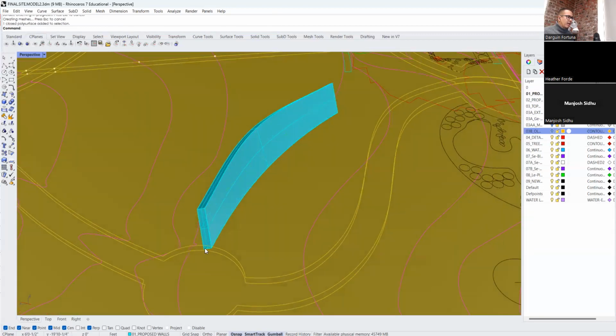Again, I used the reference path that we had before, so that's generally where you wanted it before. Move the piece up and down. There's other options, and I don't want to confuse people, so I want to just keep it simple. We used the reference path before to create a curved, beautiful, clean path. We moved that path up and backwards and accelerated it with the control points of that curve using this curve command that we used to draw it. And then we just did a loft, and the loft created a surface, which then got modified with the offset to give it thickness. And that gave us this.